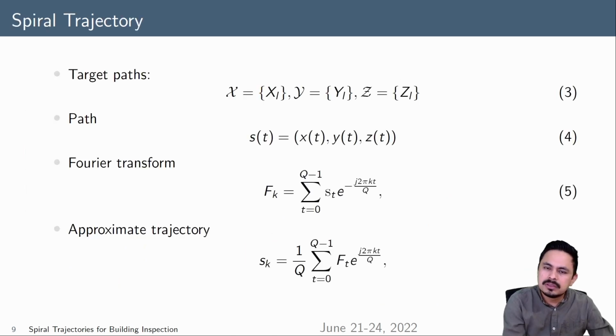Here we map all those signals to the frequency domain using the Fourier transform. Specifically, in our implementation, we are using the fast Fourier transform. So using the transform, we can obtain several components, each component related to a frequency. The combination of those frequencies can reproduce the original signal.